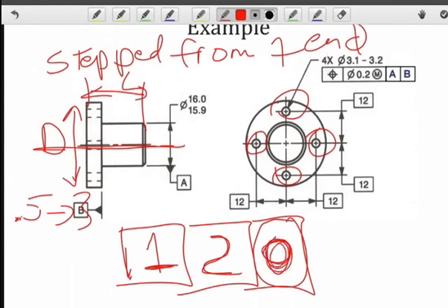So here's our Opitz code, at least the beginning of it. We still have 6 digits to go, but you get the general idea. Based upon our design specification, we can come up with perhaps a part family where the first 3 digits are 1, 2, 0, and then they would proceed through the same set of processes with perhaps some slight variations.